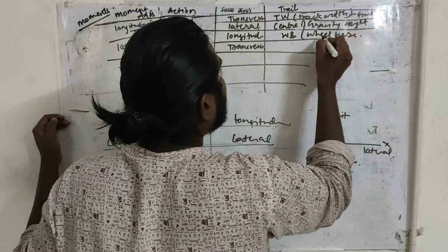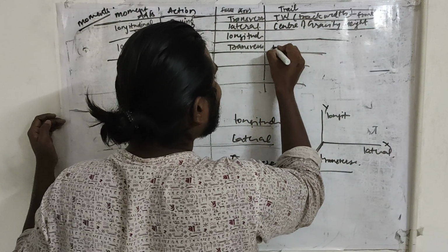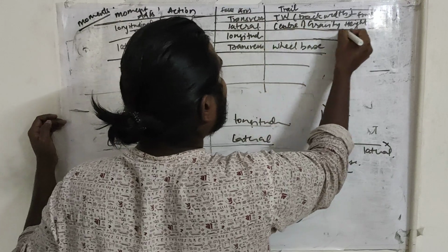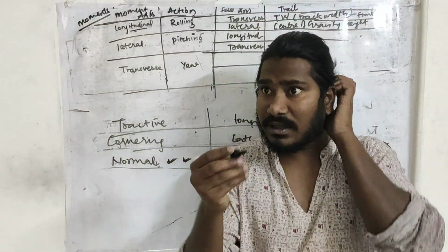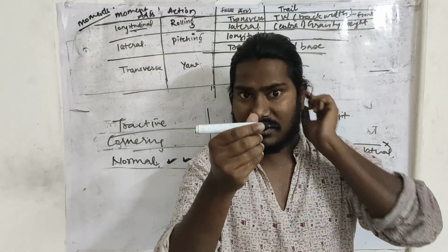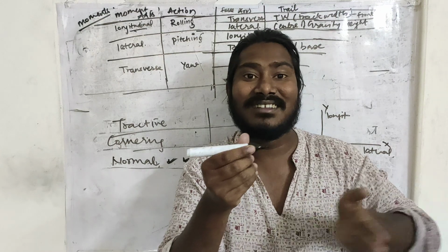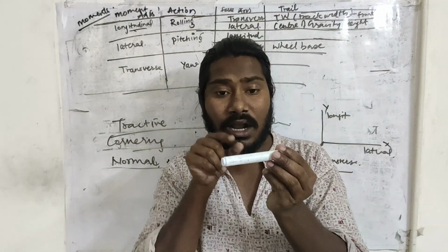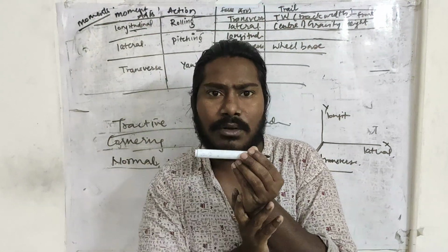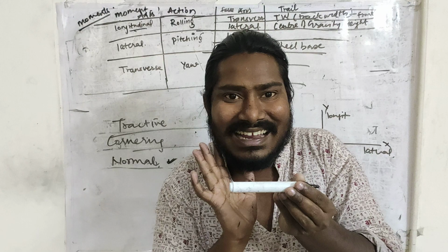For the transverse, normal forces are the transverse, right? Wheelbase. Okay. And what about the longitudinal forces? Now this is my axis, and these are the forces that are acting. The longitudinal forces that are acting, the tractive forces that are occurring, or the inertial forces, or the D'Alembert forces, particularly you can say the D'Alembert forces. Either the D'Alembert forces are acting at the height of